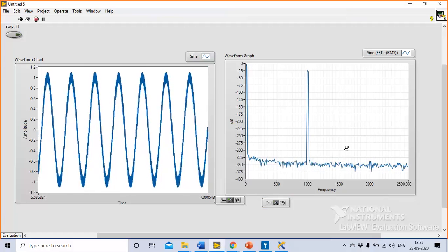We just zoomed from that, I guess. But my noise floor is at a very minimal value, minus 325 dB, right? Theoretically not possible, practically not possible, but the noise floor is very low. So I want to remove this signal. I can use any frequency lower than this signal, right? If I set my cutoff frequency as, let's say, 600 hertz, then I will still be able to cut this off.